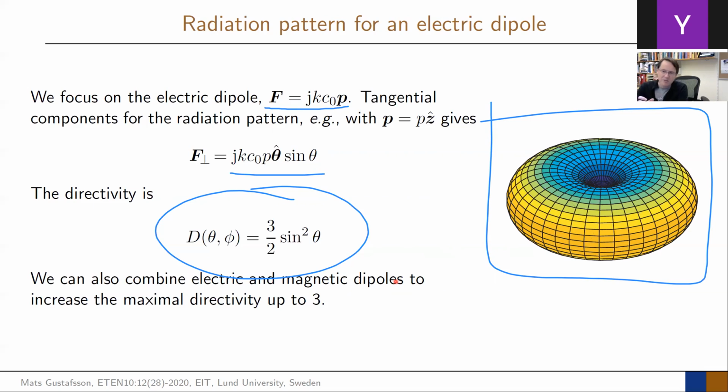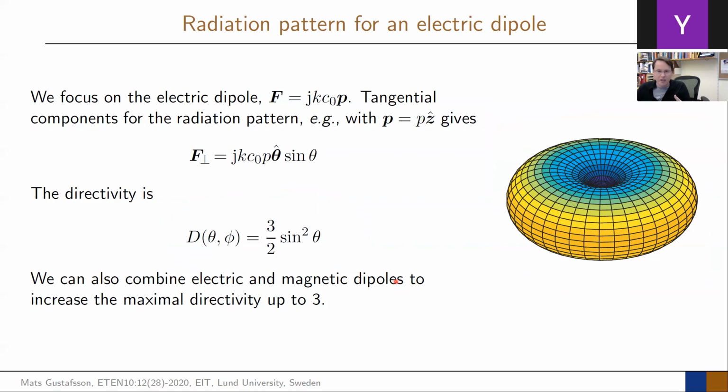And the details of your antenna don't really matter for this. It still starts radiating like this. So when something is small, don't expect it to have a very strange radiation pattern. It has a very simple radiation pattern. And now it is, of course, when we really have gone on to electrically very small structures. When they start to go up to being like half a wavelength, then you can start to change the radiation pattern. But when you shrink them, so lambda over 5, lambda over 10, this is the pattern that you start getting.